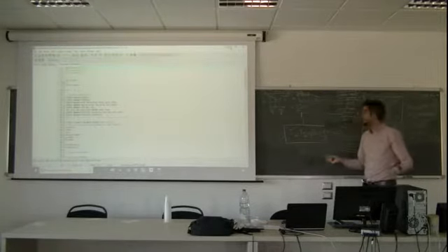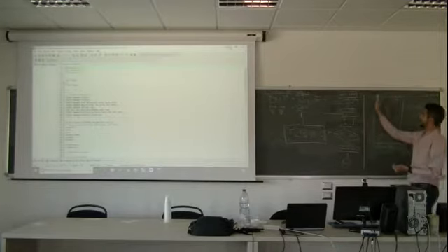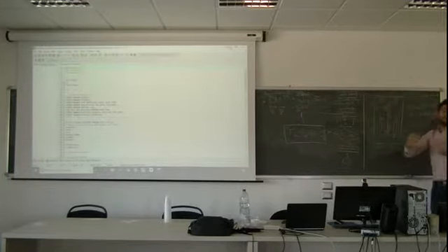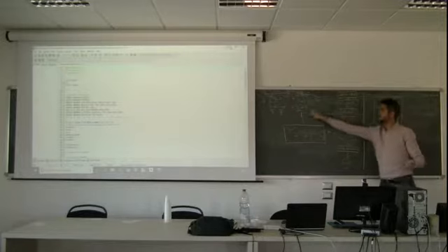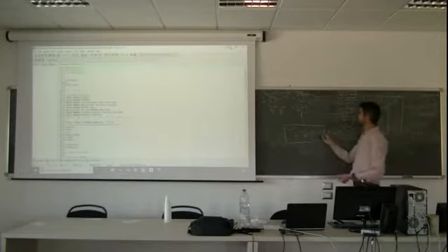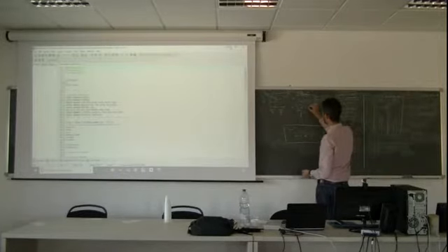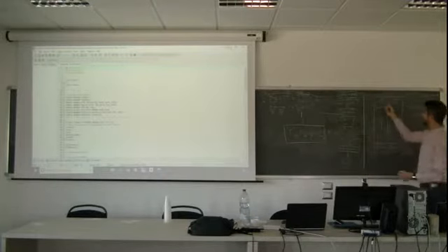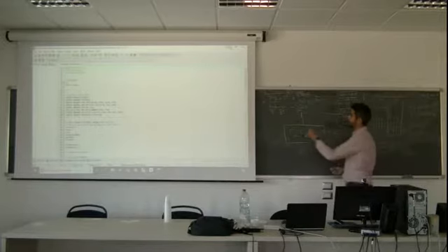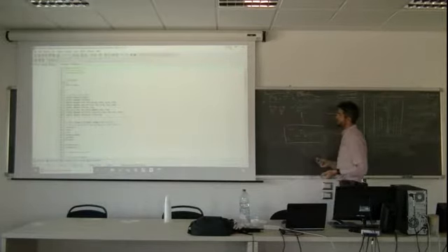Because it's Cartesian coordinates. We have the same surface of heat transfer here and here. We have nothing cylindrical, so we can put just S. Plus QB. QB is 500 watt per cubic meter, so I need to know the volume.